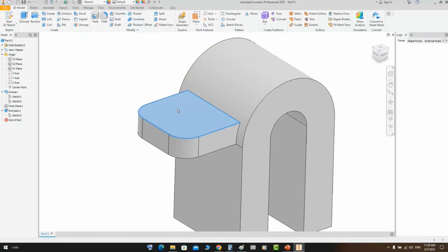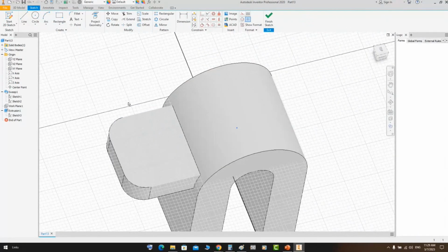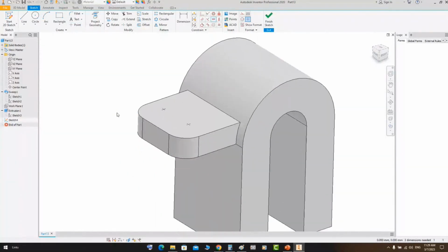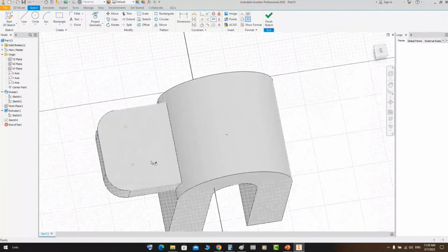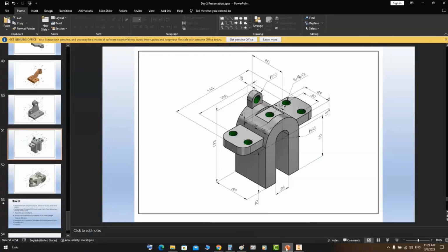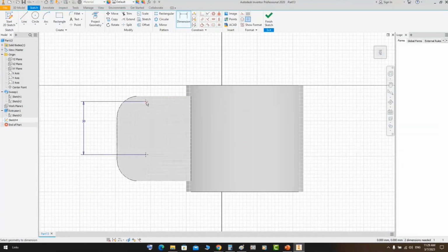So let's select the surface and add 2 points and make those points as vertical points. Sorry, I clicked on the sketch to finish the sketch, but I should define the spacing, which is 30 millimeters, and we would like to align it.